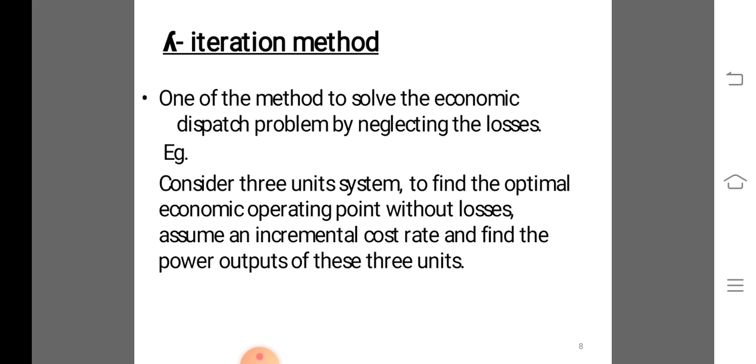With two solutions, we can extrapolate or interpolate the two solutions to get closer to the desired value of total received power. By keeping track of the total demand versus the incremental cost, we can rapidly find the desired operating point. If we wished, we could manufacture a whole series of tables that would show the total power supplied for different incremental cost levels and combinations of units.